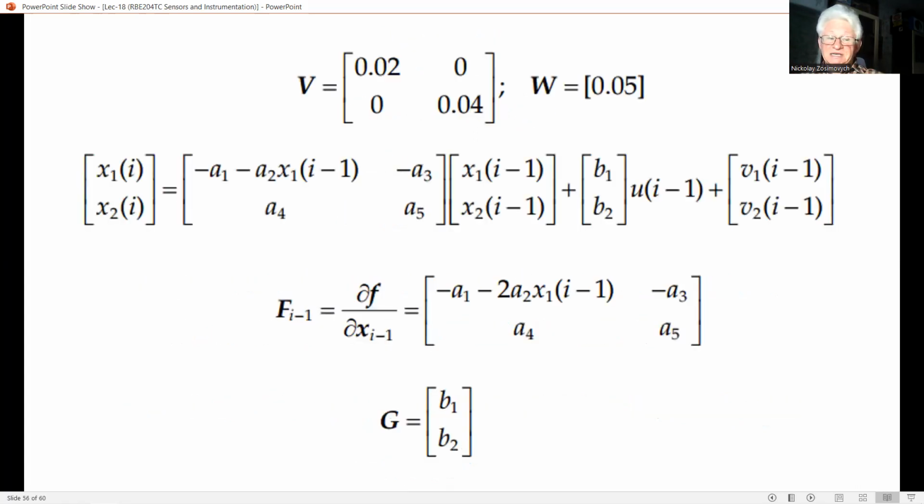For the purpose of the present example, the measurements of the absorber speed are simulated values generated by the nonlinear model of the system with added random noise, and the model input disturbance and measurement covariance matrices are taken as these two expressions for V and W. The discrete model may be expressed as the second matrix here on linearization using the first term of the Taylor series expansion as a first derivative.